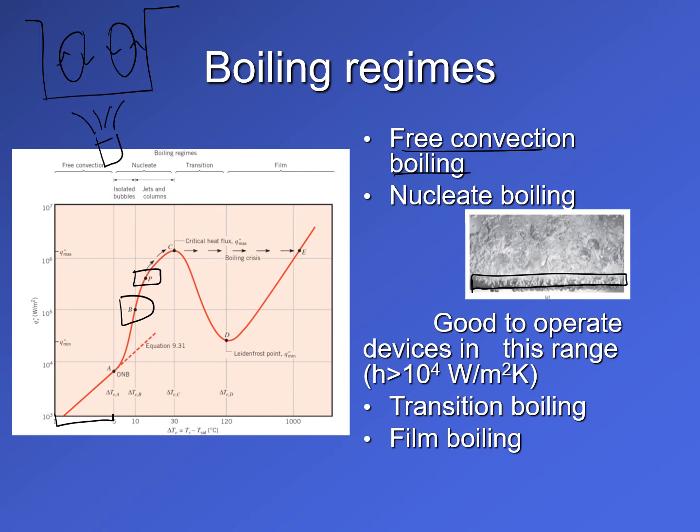Most of the surface is covered with vapor bubbles because of lots of nuclei of vapor. So what happens is there is some sort of resistance that starts because of the interference of bubbles above the surface, as well as the coating of vapor that starts to form on the surface. The rate at which the heat was increasing starts to decrease.